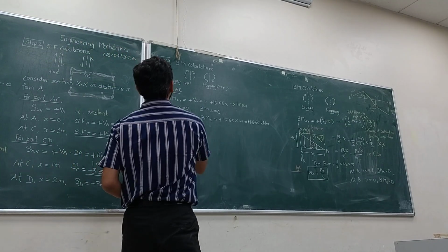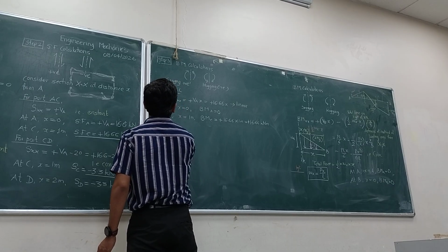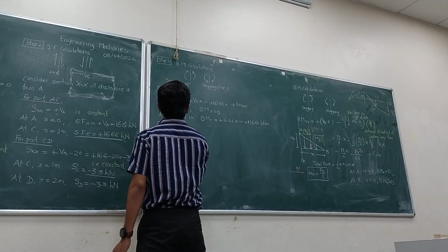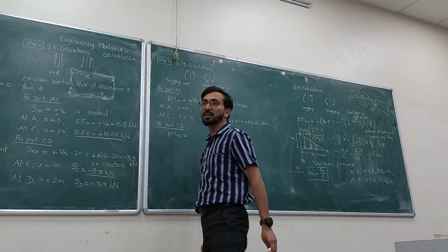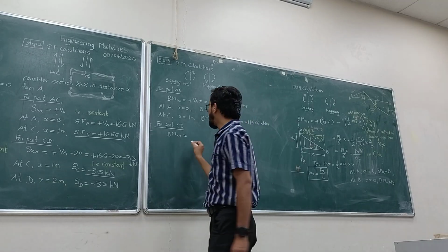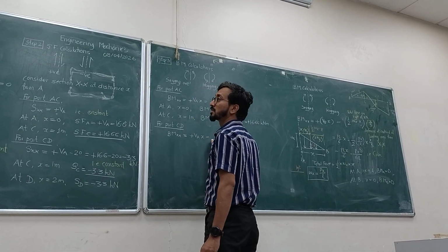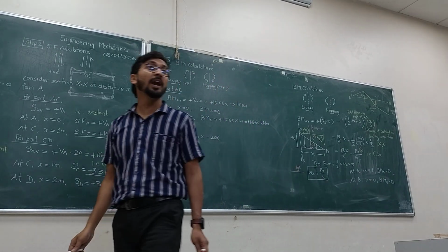Next, complete the right. So bending moment for part CD. Bending moment at xx is equal to, who can tell? Plus VA into x minus 20 into a, who can tell this? 20 into what will come?